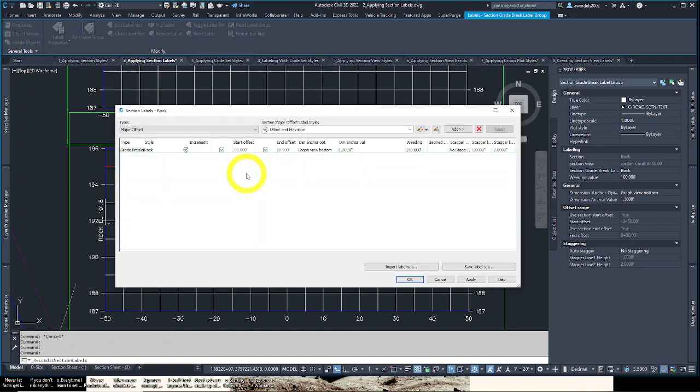And this will open up and we have a weeding column. It wants us to change the value to 5. So weeding basically in short in other areas of Civil 3D, it's like picking weeds in a garden. You're picking out things, entities to make it more fine-tuned. So if you have 100 vertices in a thick polyline, you weed it out to say like 5 efficient ones.